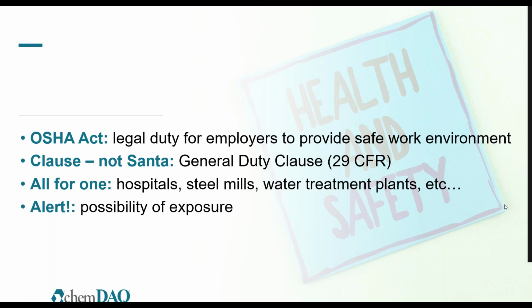To Richard's point, there's really 3 levels typically you can look at. Even peracetic acid, which doesn't have OSHA recommendations or regulations yet, still has a 0.4, and correct me if I'm wrong, Richard, but 0.4 over... And that's actually over 15 minutes. I think I said 8 hours before. It's 0.2 over 8 hours, and it's 0.4 over 15 minutes, correct? Yeah, the ACGIH is 0.4 over 15 minutes. It's a STEL TLV. Right. So at the moment, there isn't an OSHA PEL for peracetic acid. Cal OSHA has proposed 0.2 for the 8 hour.